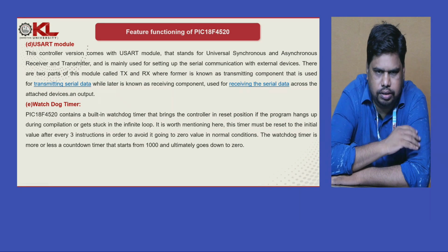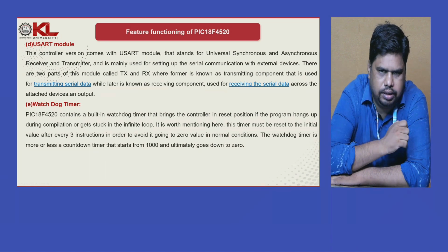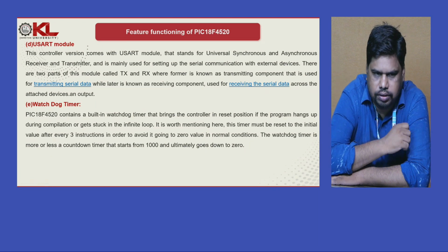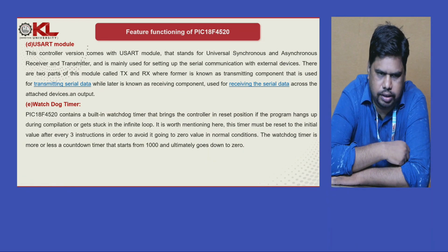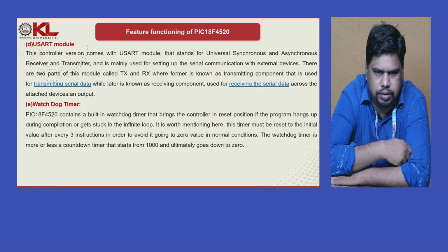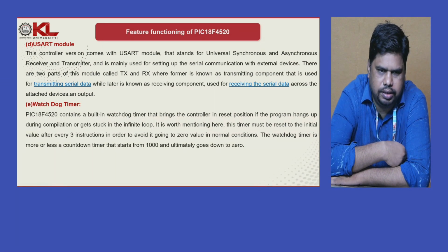So this is the working of USART here in the PIC 18F452 microcontroller. Watchdog timer is one of the important characteristics of this PIC. If a program hangs during compilation or gets stuck in an infinite loop, this timer must be reset to the initial value after every 3 instructions in order to avoid it going to 0 in normal condition. The watchdog timer is more or less a countdown timer that starts from 1000 and ultimately goes down to 0.